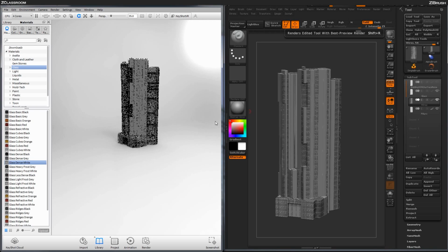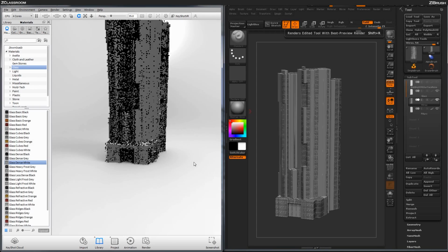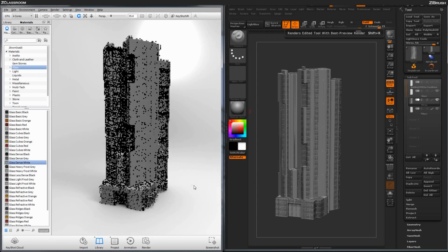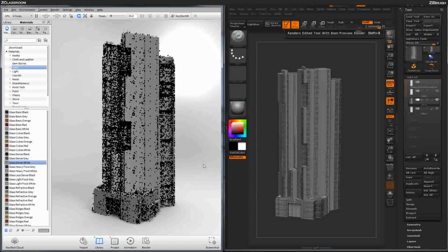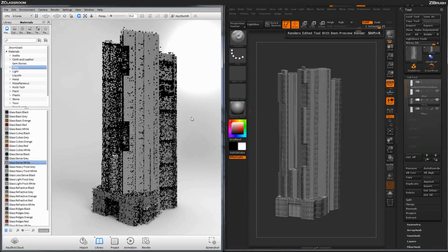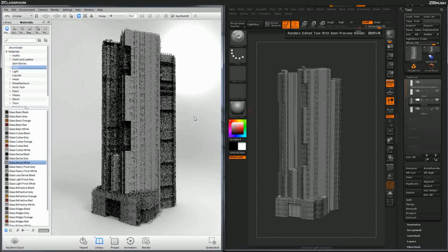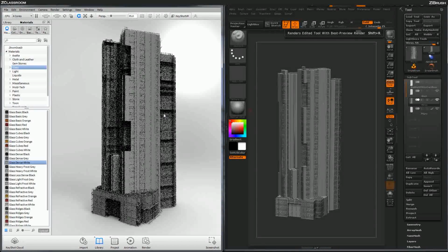I'm going to reposition this model, rotate it around, and zoom in by holding Alt and clicking, and then holding the middle mouse button to reposition the model in the scene. KeyShot will keep rendering your scene the longer you let it sit, so if you manipulate the camera, it resets that render, and as soon as you release, it continuously renders and the image gets clearer and clearer. This looks like a pretty decent angle.